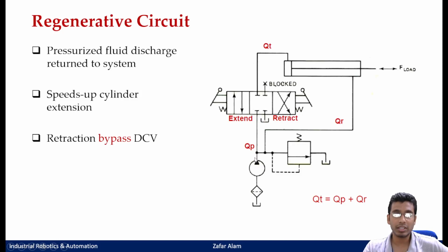The retraction, the moment it is applied there, the retraction would be only from this portion. That means your pressurized line would actually go through this, and it would not go through the DCV. It would go through this, and it would actually just retract the cylinder backwards, and then you can have your drain position here. Okay, so how is the regenerative circuit?